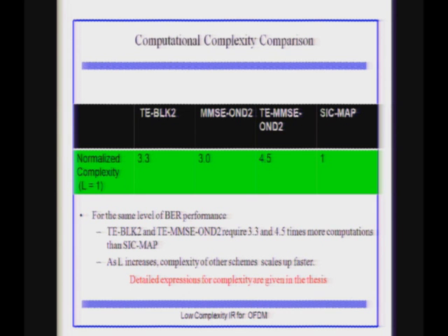So for example, in the 802.11 transmitters or even receivers, they do all sorts of gimmicks. They try to power it off, put it in a standby mode, and bring down the power islands to a different voltage, 1.8, whereas the rest of the things are at 3.3 volts, and do all sorts of gimmicks in the silicon to bring down the power. So when we have lesser power, that is one thing.